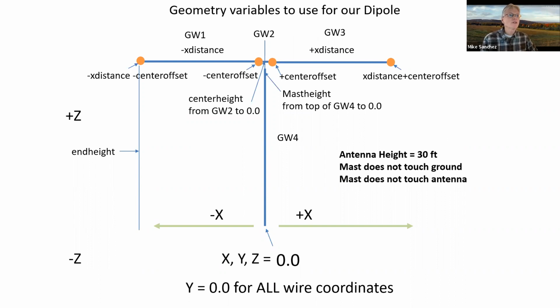So if you have a vertical or any kind of antenna that starts at the ground and has a bunch of ground radials, then NEC 2 will not work. What will work is if you elevate them, and you'll learn a lot from doing that, and I have actually done that. If you elevate the antenna slightly off the ground, then you'll get an accurate result.